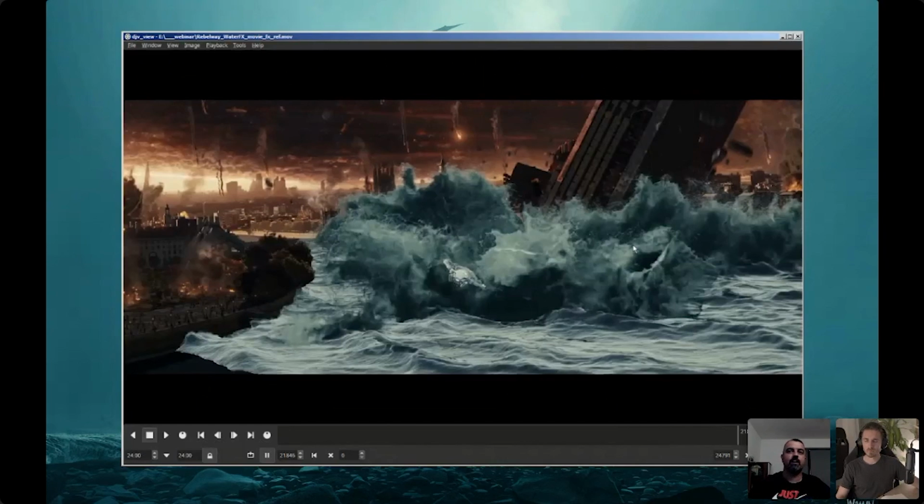Do the 5-hour sim. Try to add many whitewater layers that can be split on multiple machines. Like, every machine 50 million. At the end, you have 1 billion particles of whitewater. So you become faster instead of waiting 20 hours per iteration on a high-res sim. And at the end, you don't see anything.